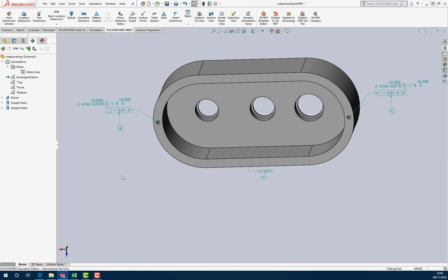And that information of relativity from one casing to another is translated through the dowel holes. That's the thing that locks the two casings together, or locates them relative to each other, those two dowel holes. So everything needs to be measured off the dowel holes. And when the two casings come together, they're coming together on this face. So therefore you need to be measuring from that face.